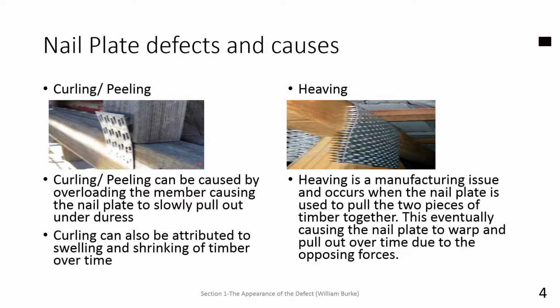Curling or peeling. Curling or peeling can be caused by two issues. One is the overloading of the member, causing the nail plate to slowly push out under duress. Curling can also be attributed to the swelling and shrinking of the timber over time.